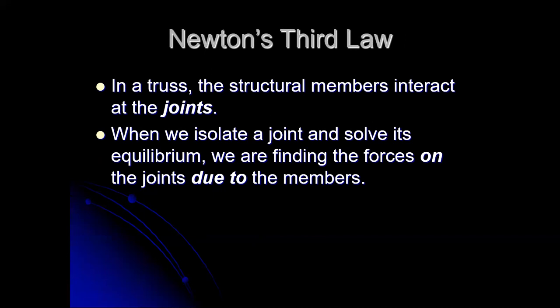We're looking at the reaction forces. Think about a simpler example: just think about standing on a floor. When you stand on a floor, the force that you're applying to the floor is down, gravity. But the force the floor is applying to you is up, equal and opposite. It's exactly the same situation in dealing with a joint and a member. When that member is exerting a force on the joint, the joint exerts an equal but opposite force on the member.